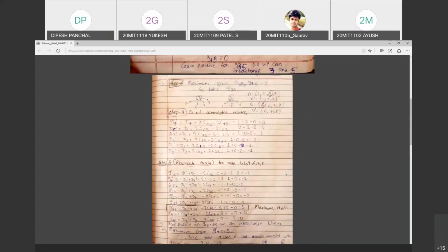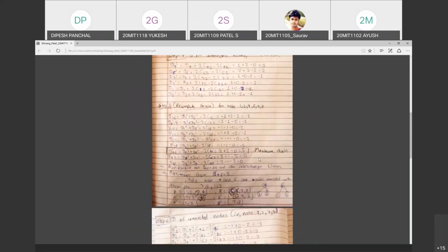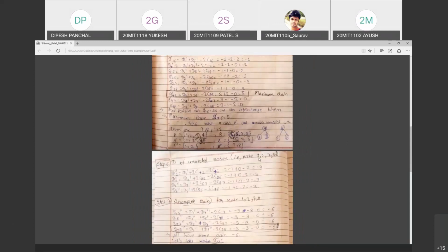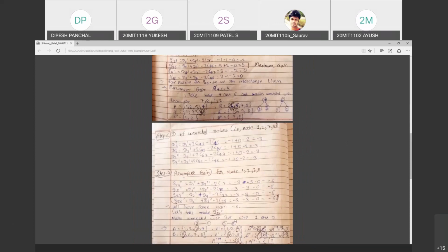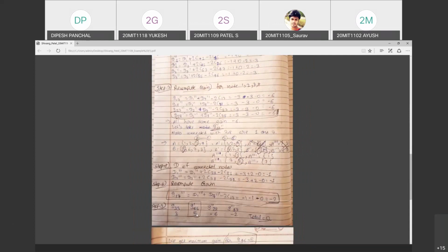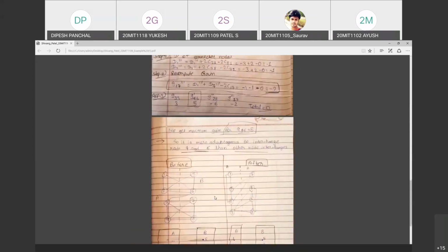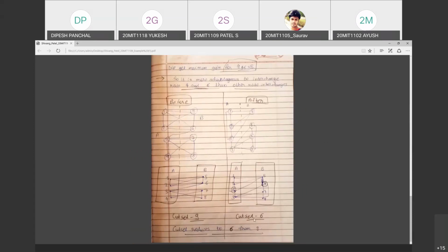I hope all of you also did it. This is 3 and 5 swapping. Parthiv, you can find your answer here. And then 1 and 7 is swapping, and then total gain is 0. He selected this 5, but one additional step you have to apply. You have to do the cumulative addition of all the gains and see where gain becomes maximum. He got the answer of 6, but still 6 is a large number compared to 9. So take the cumulative addition. That is the only one additional step you have to add.